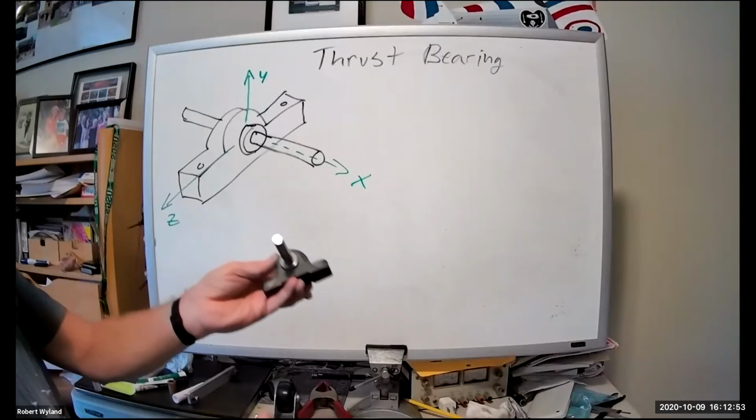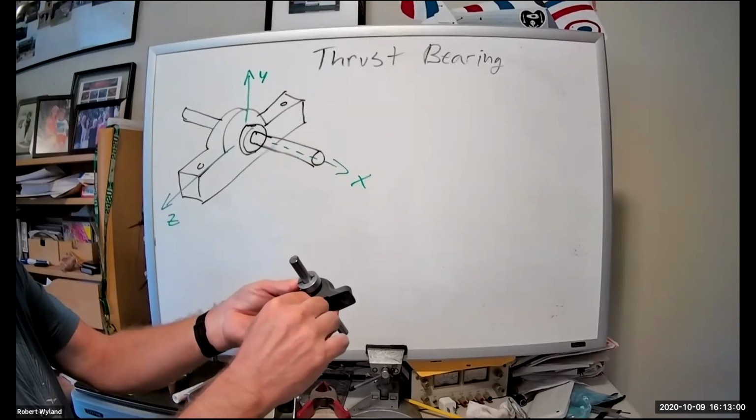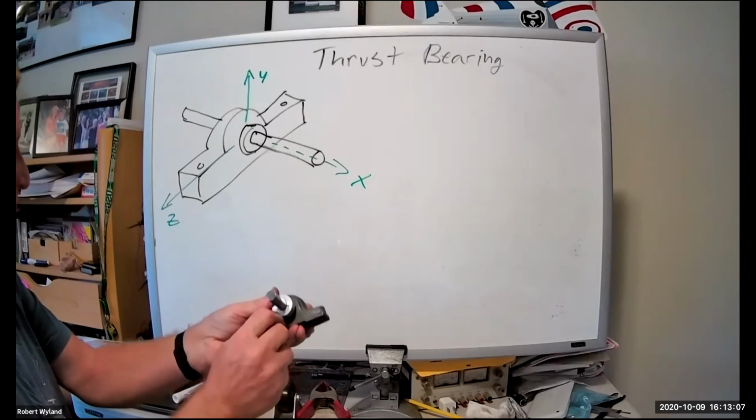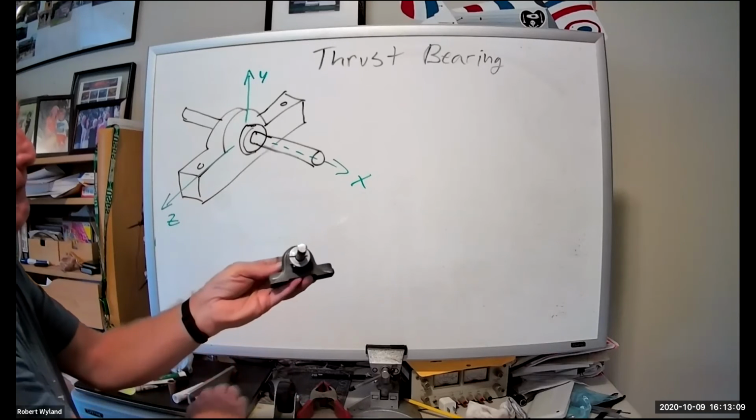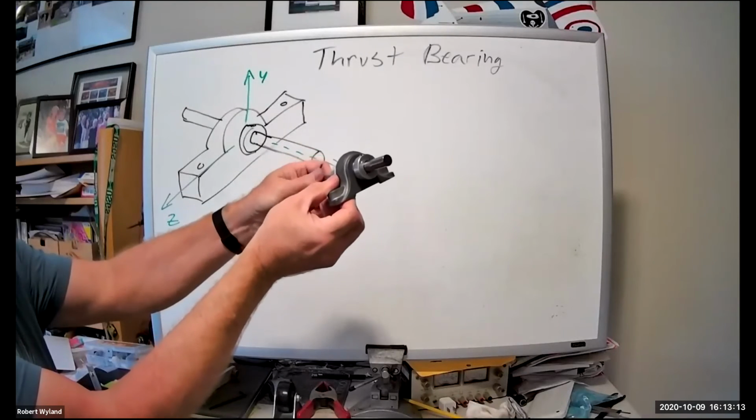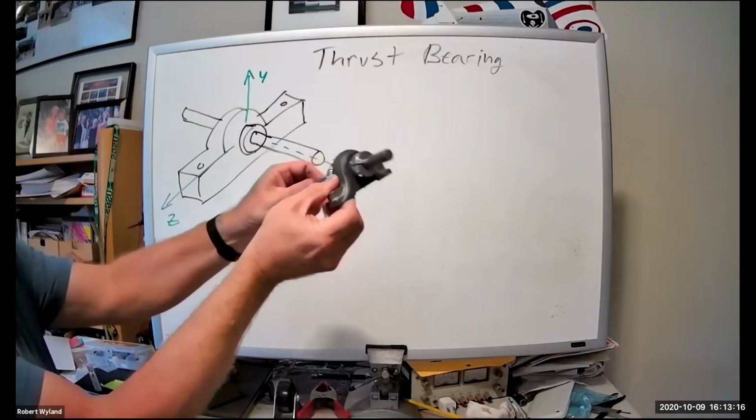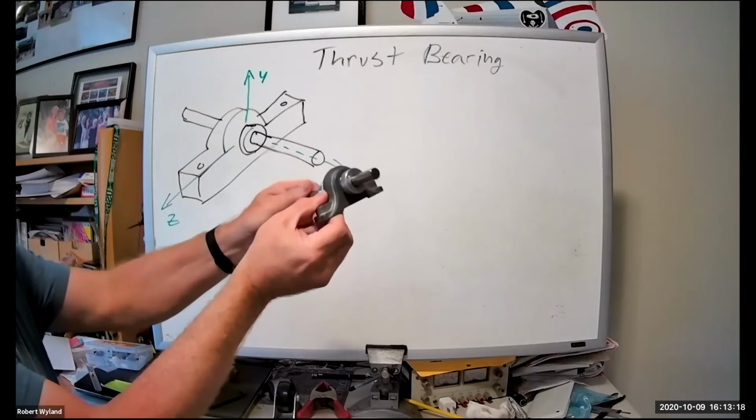So again, I install surface to ride on. And so this thrust bearing, does it lock it in place? I'm not sure what it does in the first place. Yes, we're getting there. And yes, you're correct. It locks it in place. It blocks the shaft from sliding along the x-axis. Okay. Does it prevent it from spinning on the x-axis as well? That was the whole point of those little balls inside the blue piece. Now you can see that I've got this assembly. You see it freely rotates, and you can see that it doesn't want to slide in and out any longer. Okay.